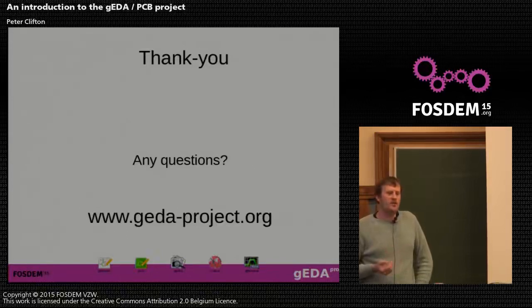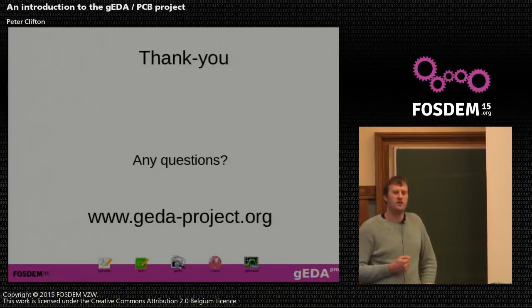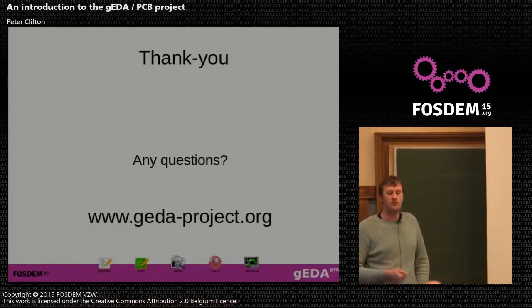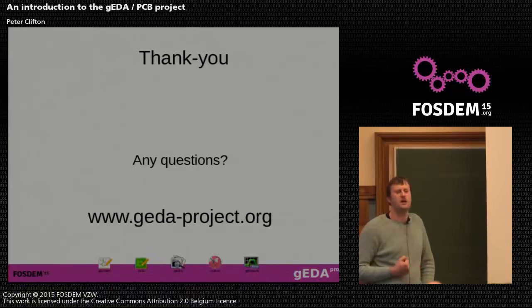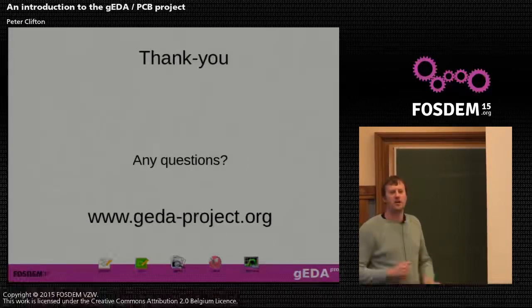But fundamentally it relies on maybe you having one schematic and the net name that is in that schematic being the correct net name by the time it got to PCB, which is not necessarily the case in general, because you might have a hierarchy of schematics, and the schematic you're actually working on in the schematic editor could be 3 levels deep into a hierarchy, and the net name within that may well not be unique within the design. So in order to do it properly, I think we need a concept of connectivity that is kind of live, so a live database that understands this design is open and it starts at this root schematic. So if I'm within the hierarchy, I know where I am within that hierarchy.